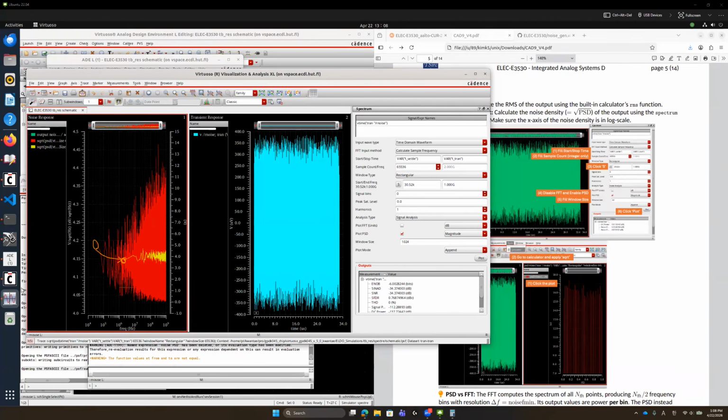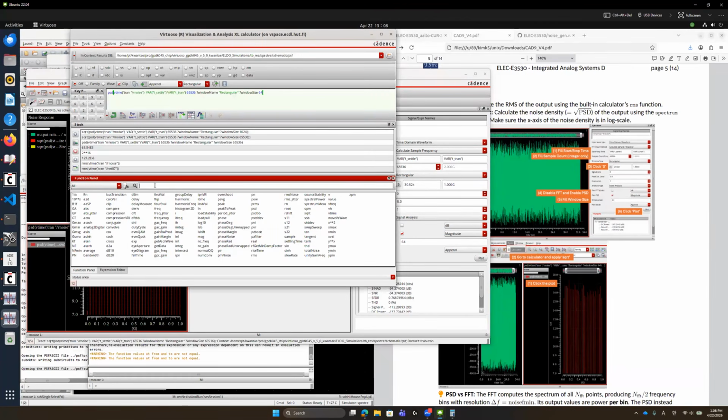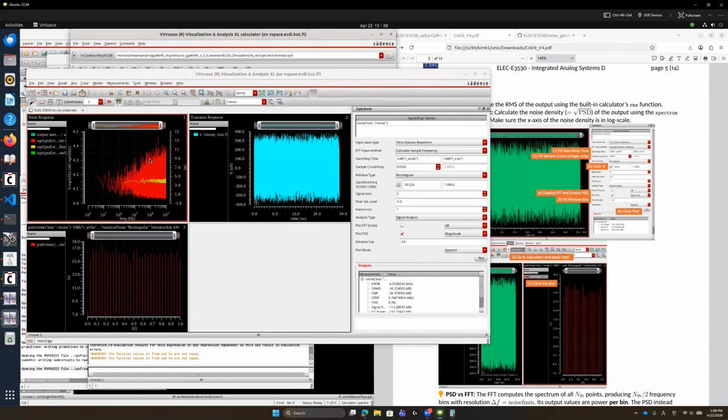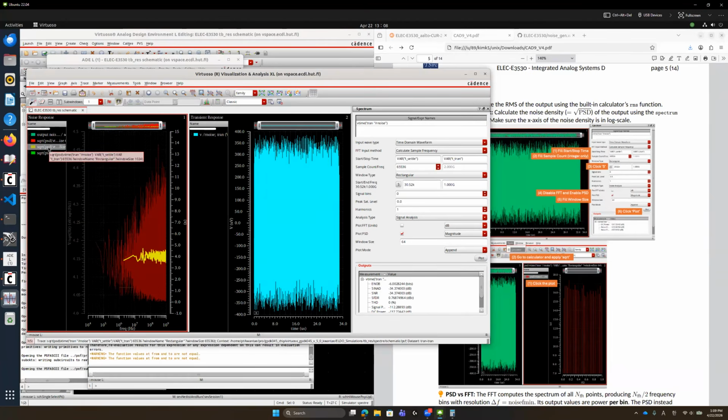Of course, you can do even further, for example, as shown here in this guideline. Well, you can try 64 or maybe 32, but definitely you may lose the frequency resolution and minimum frequency limit. SQRT. Then you can see that it is much, much cleaner compared to the red case, yellow case, and green case. So we are running FFT over randomness. So that is the reason why we need this kind of average.